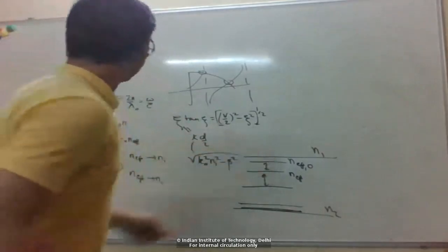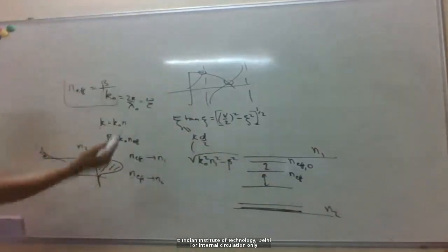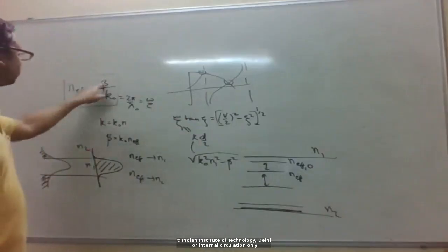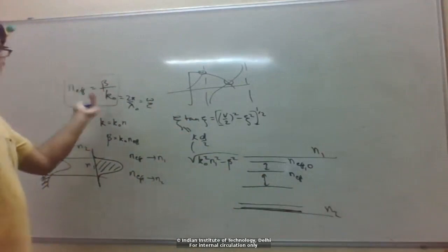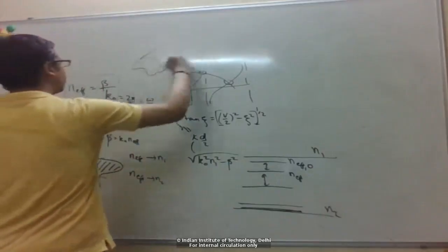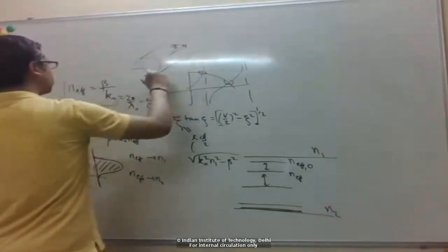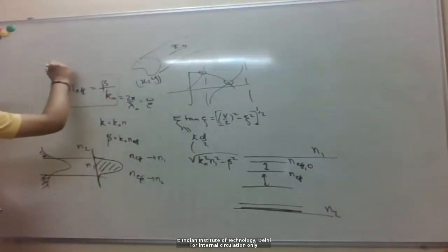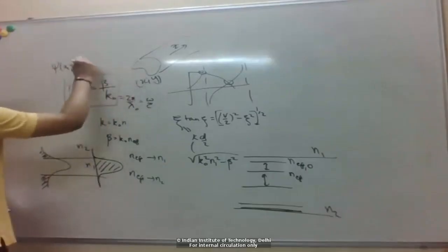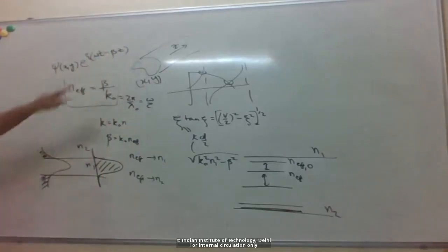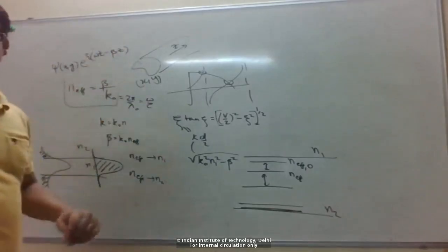No, as I said, we just discussed, n effective is true for any waveguide. We take any mode in any waveguide and find the beta, it will have a propagation constant. For any waveguide, you have a cross section in xy and the mode is traveling in the z direction. So for the mode profile you can write some function in the xy plane times a phase like that. And what the values of this beta are, we solve from the wave equation.